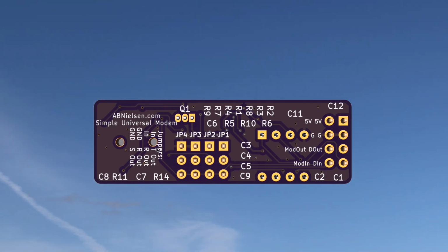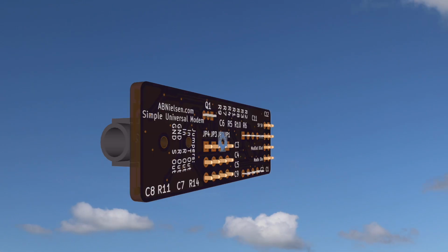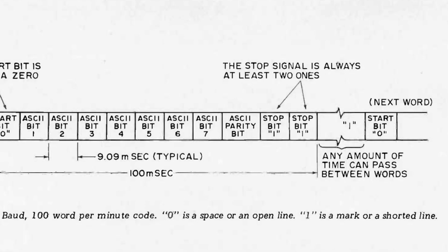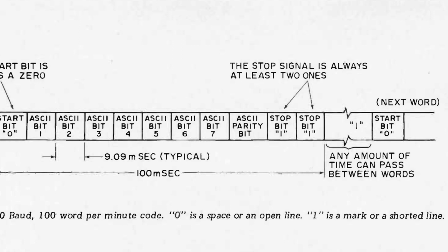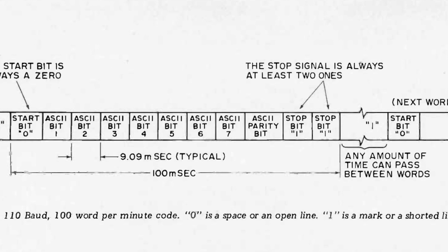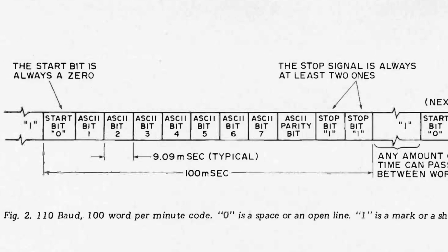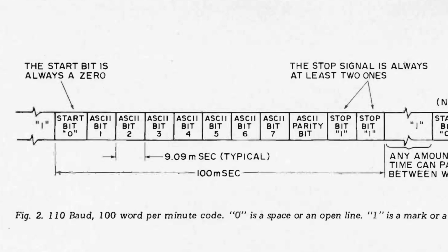I've taken some liberties with the Kansas City standards with my actual software implementation. Excuses: I haven't had the time to write more than the basic routines to store and load data, and I've skipped the error correcting and start and stop bits completely for these demos. You can expect to see an update in my 6502 single board computer repo on GitHub soon to rectify that.